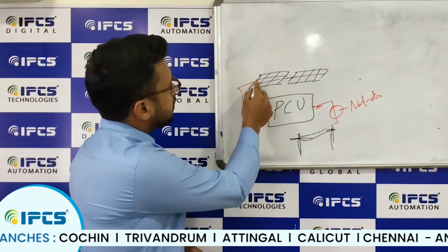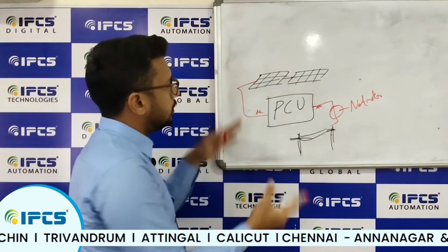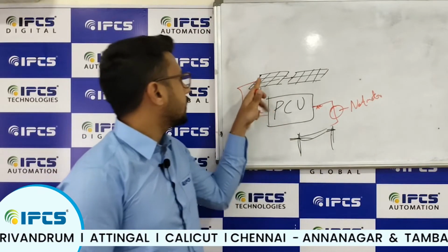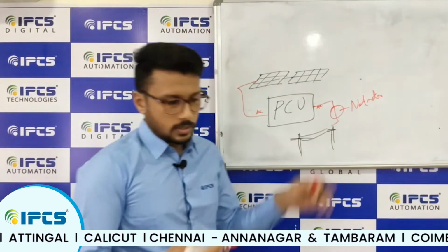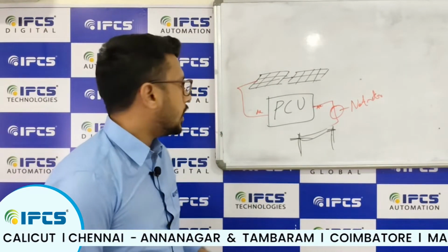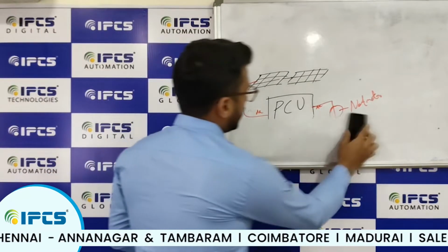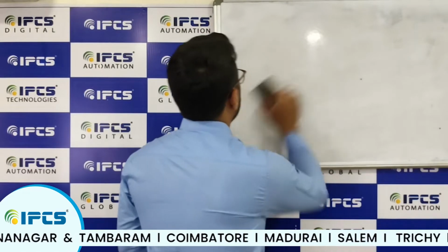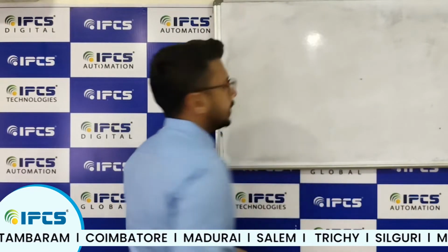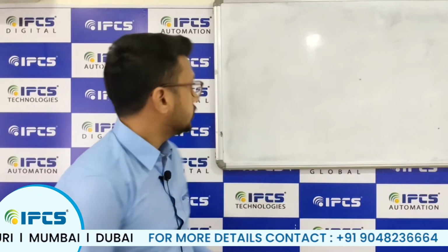So this is the case of an on-grid solution, and it is to be noted that the distance between the solar panel and the inverter needs to be short, because we are carrying a DC voltage. So as we know, DC is not good for longer distance transfer. Okay. So that's the main design, how to connect these panels with the inverter.